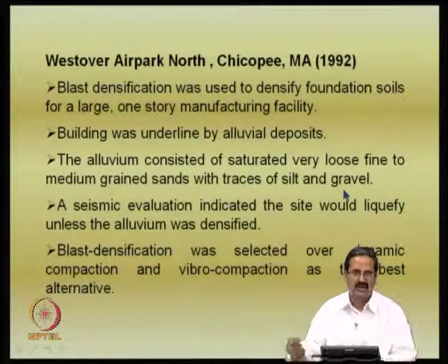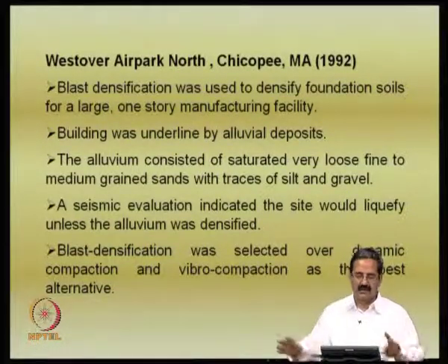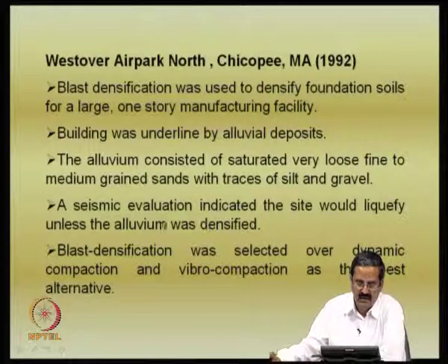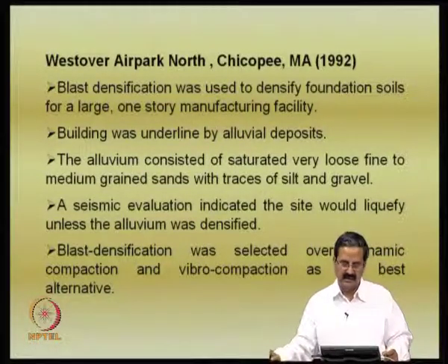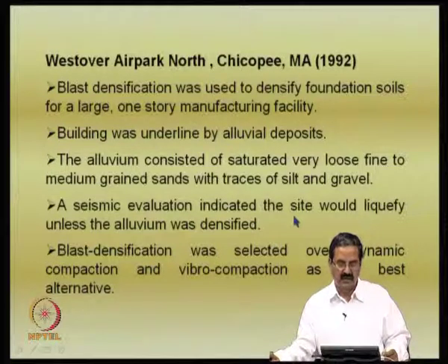So, the soil is very liquefiable. A seismic evaluation indicated the site would liquefy under the seismic event unless the alluvium was densified. If you do not densify the alluvium, you could have liquefaction, which could really lead to damage to the manufacturing facility.